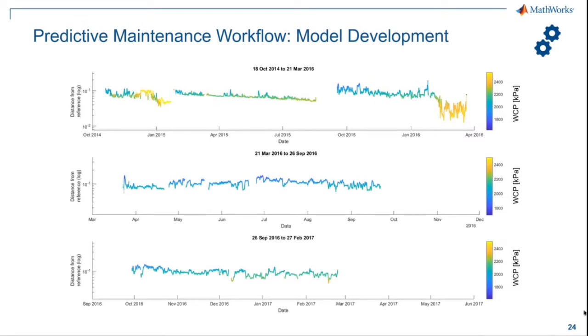And that distance between the data points and the threshold is what this graph represents, where the y-axis is the log of the distance, the x-axis is time, and the color bar in this instance represents the wheel chamber pressure. Each graph here is a separate life cycle, and we can see that in general, each graph very gradually tends to 0 over time. Because remember, the x-axis essentially represents that operating threshold which we are approaching.